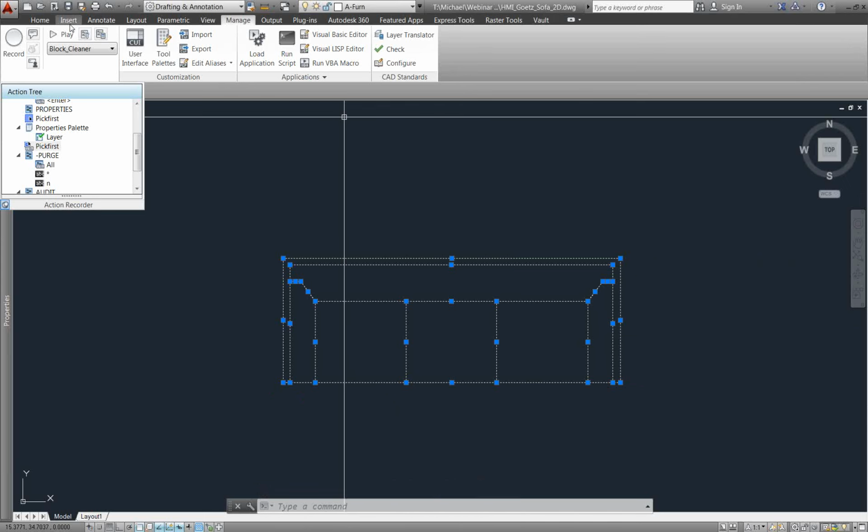So maybe you have a series of objects in a drawing that you want to run an action on. You can go and pick them first. Say you have a bunch of circles you want to select, and then modify all of their diameters to 6 without having to select them individually during playback. You can actually choose this pick first.